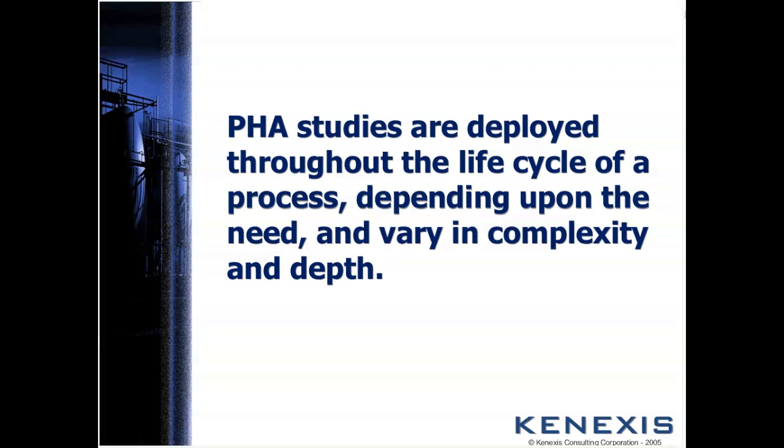You could have a mini study on design changes, a pre-commissioning study for the plant, a post-startup or revalidation study after the plant's been up and running. So PHAs depend upon concise and accurate process safety information while you conduct the study, okay? And this is developed somewhat concurrently as a process develops, and I'm going to show you how this works a little bit.